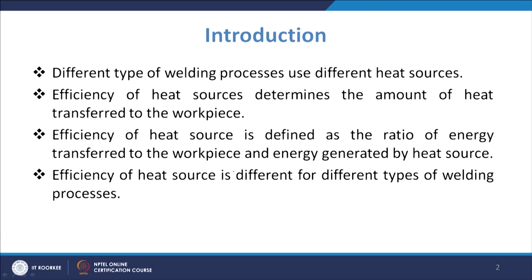Different types of welding processes use different heat sources, that is very common, and the efficiency of the heat source determines the amount of heat transferred to the workpiece. So more efficiency means that more of the heat which is generated is transferred to the workpiece to increase the temperature, so that the process of welding is facilitated.